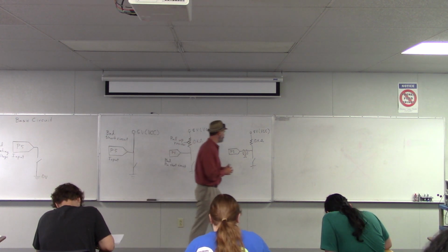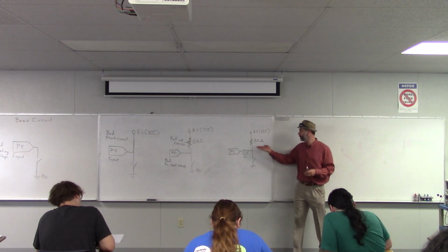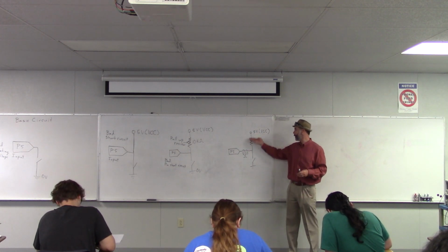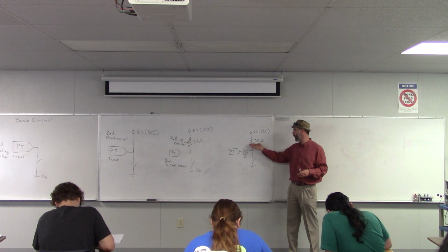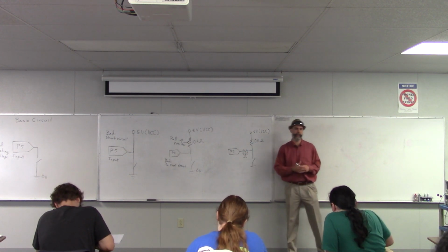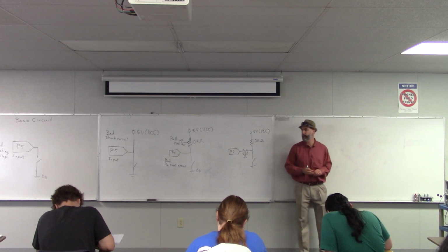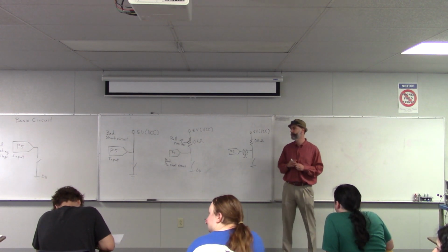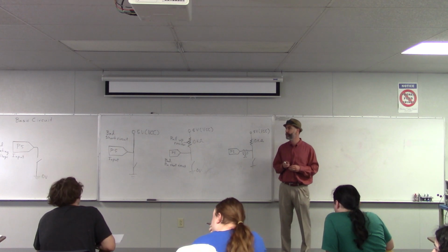Okay. So here we are. We've got our pull-up resistor that's pulling this voltage up when the switch is open. We've got this other resistor that's protecting the pin in case somebody accidentally made it an output instead of an input. Yeah. Why don't you put the resistor near the switch?